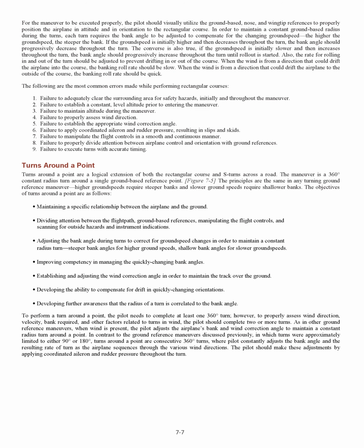For the maneuver to be executed properly, the pilot should visually utilize the ground-based, nose, and wingtip references to properly position the airplane in attitude and in orientation to the rectangular course. In order to maintain a constant ground-based radius during the turns, each turn requires the bank angle to be adjusted to compensate for the changing ground speed. The higher the ground speed, the steeper the bank.